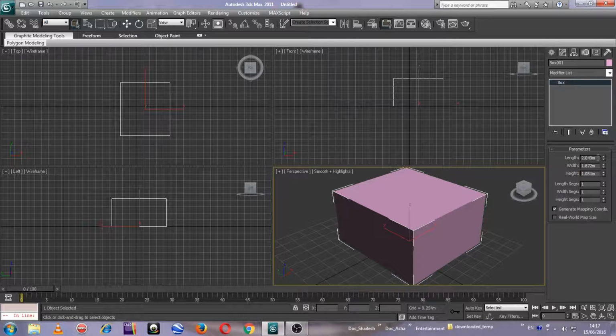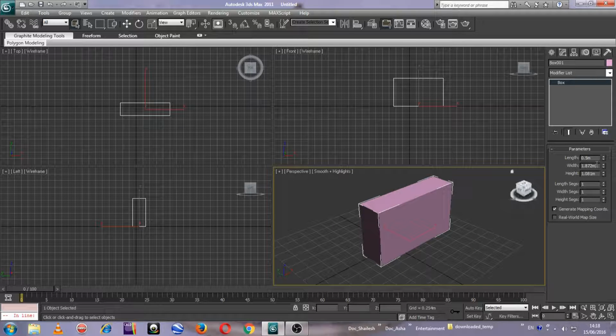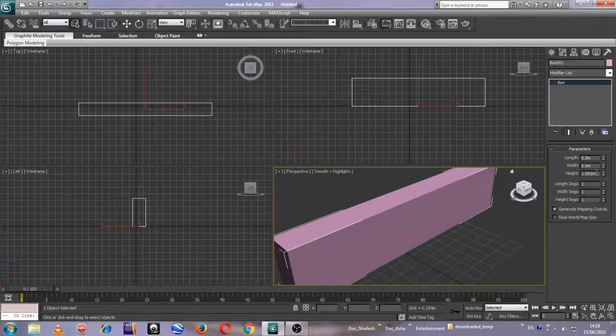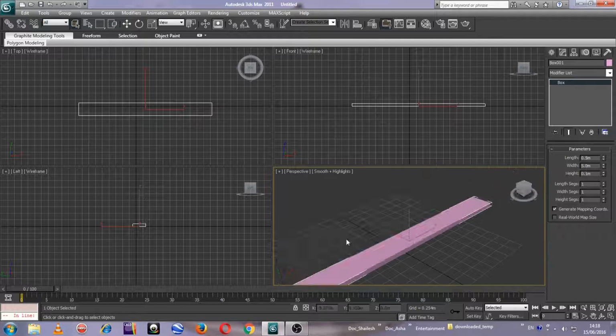But you can actually alter your length, width and height here. So for instance, I'm gonna squeeze up my object, so I'm just gonna play it 0.5, so it's gonna shrink up, or you can even play with different settings. For instance, I'm just gonna make it 5, so it's gonna stretch up, and I'm just gonna give it a little bit lower height. So you can just rescale your object over here.